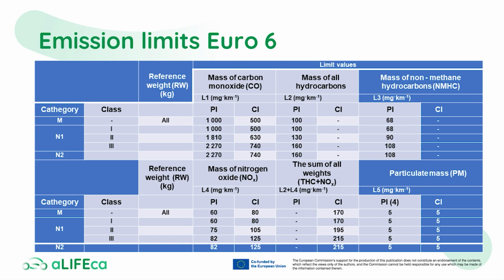The Euro 5 was the first standard to introduce particulate filters referred to as DPF or FAP for all new diesel vehicles. DPF or FAP is the filter mounted in the exhaust system and supplemented by the catalytic converter, which aims to capture up to 99% of all particles. To meet the new Euro 6 emission standards, some manufacturers have introduced selective catalytic reduction, in which AdBlue is injected into the exhaust unit of the diesel engine.